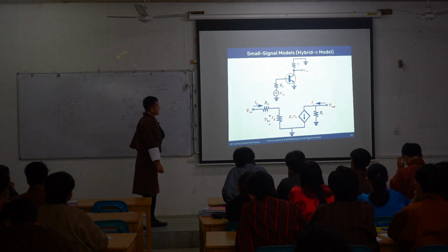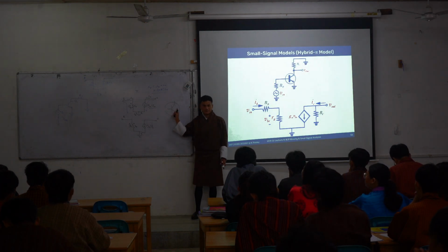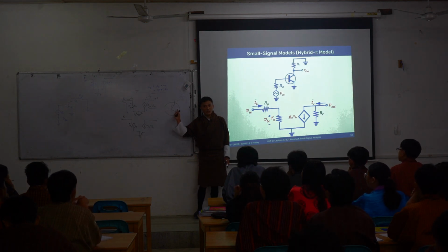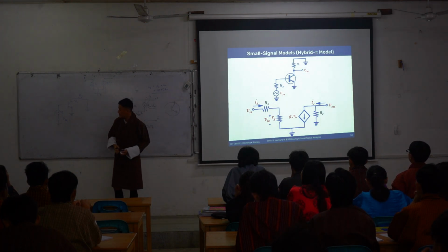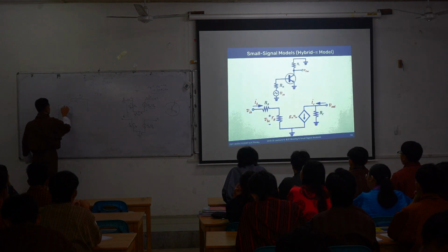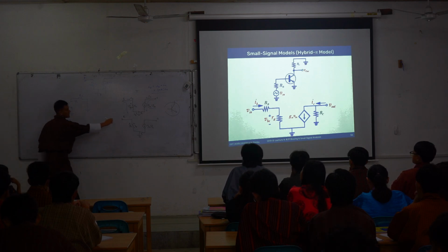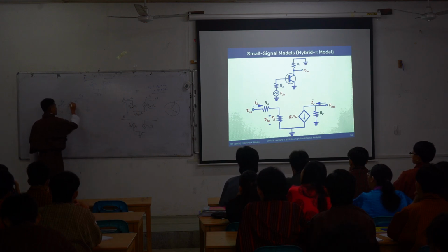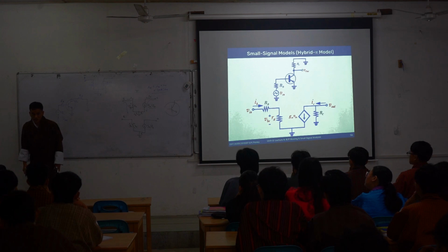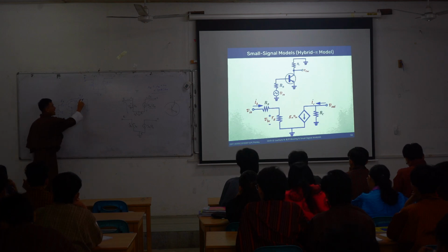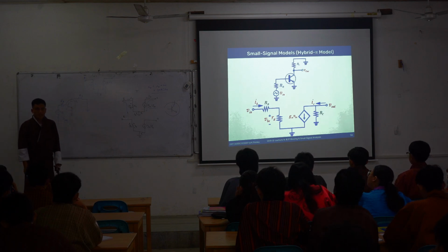Now previously, we were just representing this symbol of a transistor in your small signal model, right? Now if you compare with this circuit, we still have RB, right? This is your RB. Initially this circuit and this circuit are just the representation of this part. Now we have to include RC and RB, right?